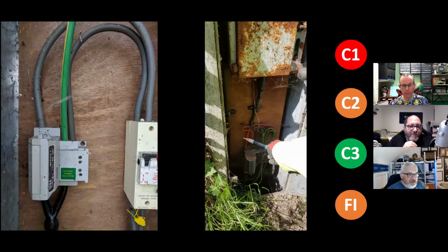My apologies, I ended up chucking a load of photos in slides, so this may not make any sense now, because I had like 100 slides and I had to go mad redacting this. 100 amp fuse, earthing terminal, PME, quite a large, hefty, chunky 35 mil going in. He is a big boy, isn't he? The earth's bigger than the neutral, pretty much. Yeah, going into an isolator.